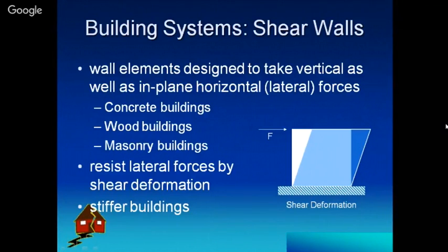And in case of masonry, as you know, brick structures are there. Brick and mortar as a unit and constituent together form the walls of houses or buildings. So every wall is a shear wall in that case for the particular type of earthquake direction. Here also it has been shown, you can see the arrow of the force direction, and the movement, the figure shows that it is parallel to that particular wall. So in the particular direction, that wall will be behaving as a shear wall for that direction.